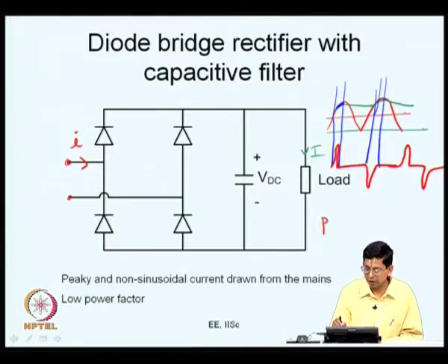This power factor is a product of what is called the distortion factor and something called the displacement factor. So, even if you have a continuous current here, if you have a highly inductive load such that the load can be replaced by a current source, the input waveform will become a square waveform. A square waveform in some sense is better than a peaky current waveform in terms of the current shape, it is probably a little closer.